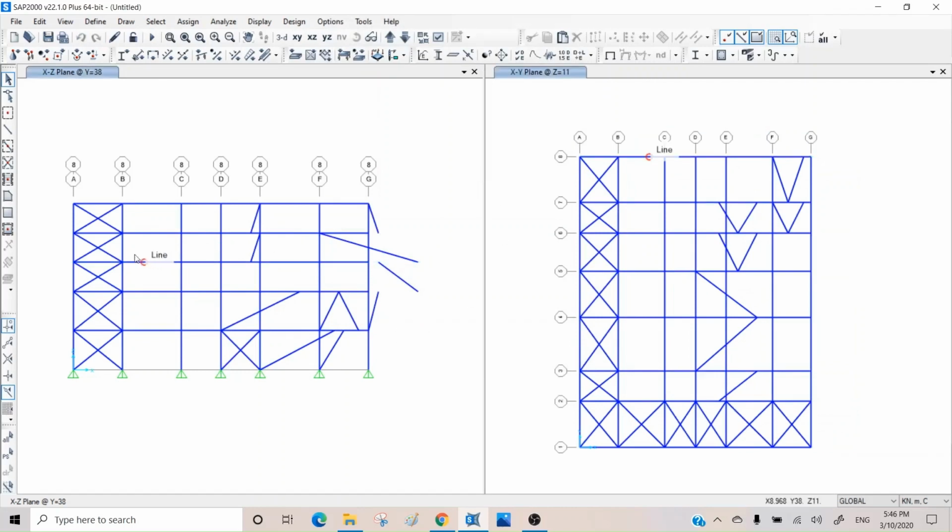There we go. So elements like X braces are correct. But the elements that are not connected to the grid lines remain the same, wherever they are. Even if you snap them to, for example, the midline of this point, it doesn't matter. It doesn't mean that when you edit the grid, it's still remaining at the mid. No, it's fixed based on the coordinates of this point.